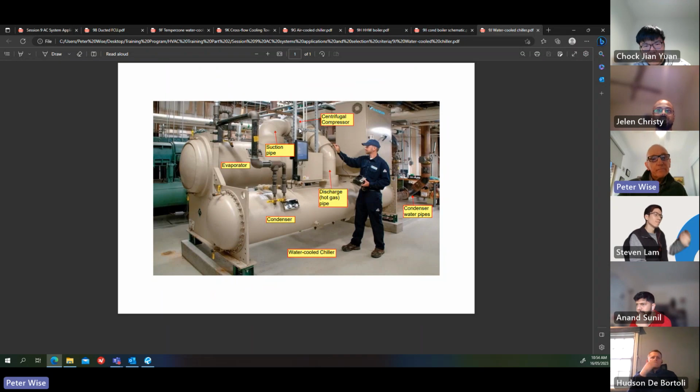And you can get them up to, with Trane chillers, or Carrier, up to 10,000 kilowatts. You'd have 2 of these chillers and some semi-hermetic. With the York chillers, or Johnson, they used to use open drive. I'm not sure what they're using there, but pretty big motors to drive these compressors.